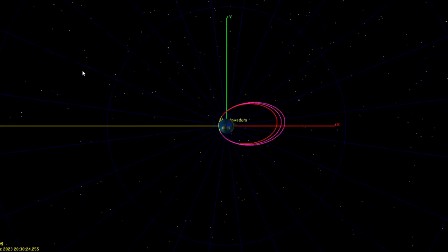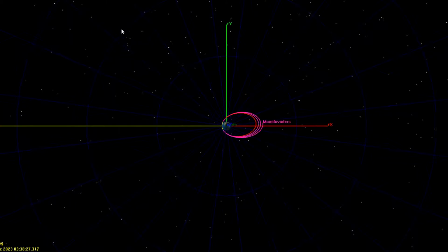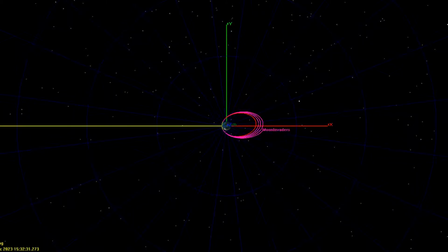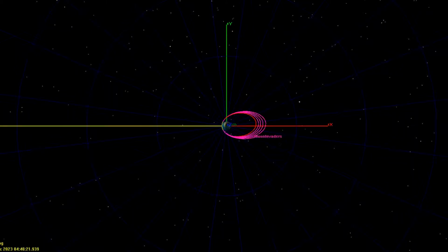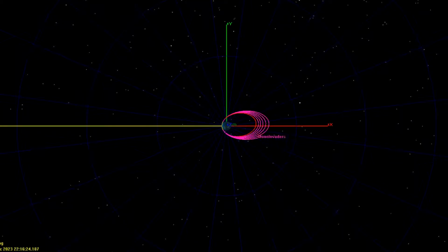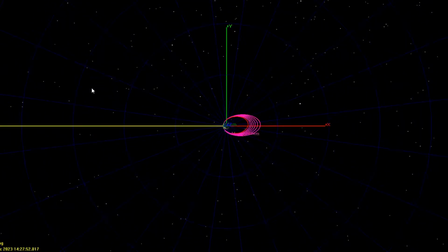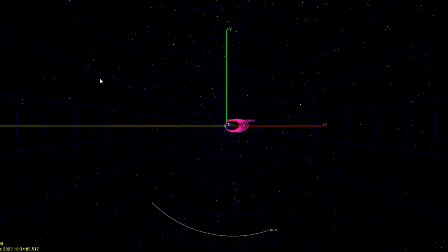To make the propulsion more efficient, the satellite will perform the finite burns close to the orbit perigee. We can calculate the delta V needed for this loop sequence using the rocket equation and the fuel mass difference in each of the loop orbits.